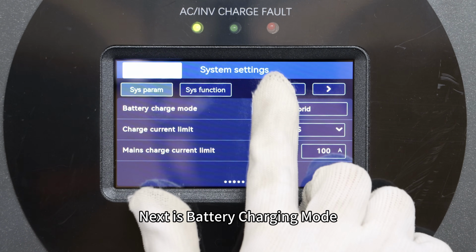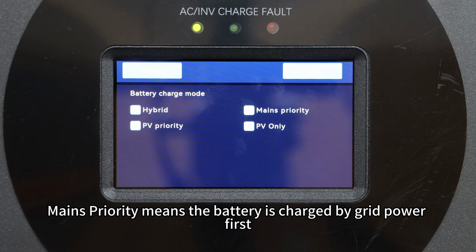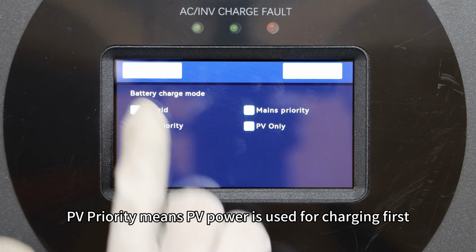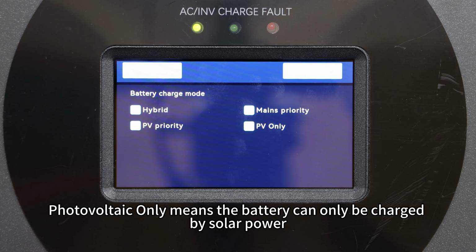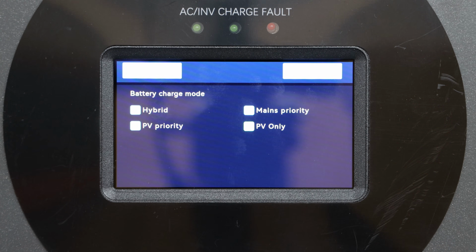Next is battery charging mode. Hybrid means the battery can be charged simultaneously by PV and grid power. Mains priority means the battery is charged by grid power first, and PV charging will only be used when grid power is unavailable. PV priority means PV power is used for charging first, and the grid will be used only when PV is unavailable. Photovoltaic only means the battery can only be charged by solar power.